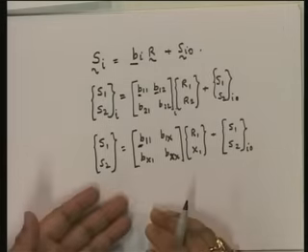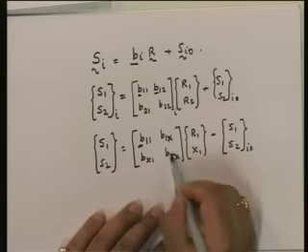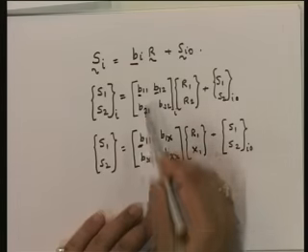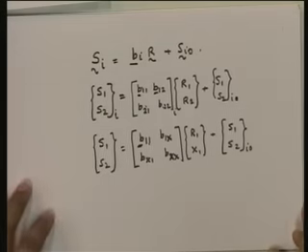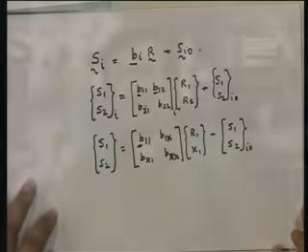No difference. These two are identical to these. The only thing is that whereas in the previous case, since R2 was an external load for a statically determinate structure, R2 was a determinate load, now we have exactly the same statically determinate structure, excepting that X1 is a redundant force and therefore unknown.